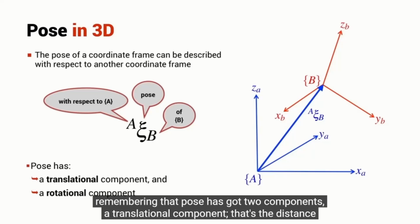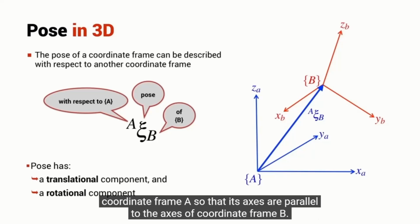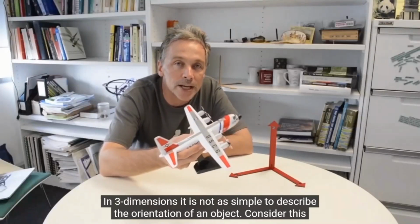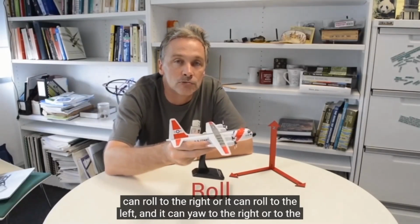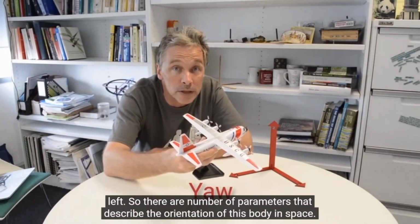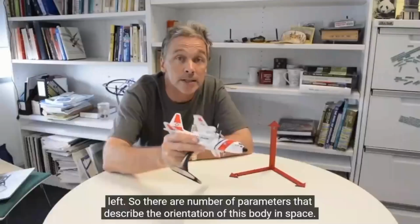And we're remembering that pose has 2 components, a translational component, that's the distance between the origins of frame A and frame B, and a rotational component. How do I rotate coordinate frame A so that its axes are parallel to the axes of coordinate frame B? In 3 dimensions, it's not as simple to describe the orientation of an object. Consider this aeroplane. There's a number of ways in which it can move. It can pitch up and down, it can roll to the right or it can roll to the left, and it can yaw to the right or to the left. So there are a number of parameters that describe the orientation of this body in space.